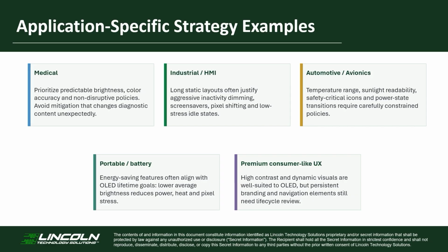Portable products benefit from a lower average brightness because it reduces power, heat, and pixel stress simultaneously. Premium consumer-like interfaces are naturally well suited to OLED's contrast and dynamic image quality, but persistent loops and navigation elements still require lifecycle review. The operating policy must therefore be derived from the product requirements, not simply copied from another display application. To make that process practical, we can reduce it to a short design checklist.